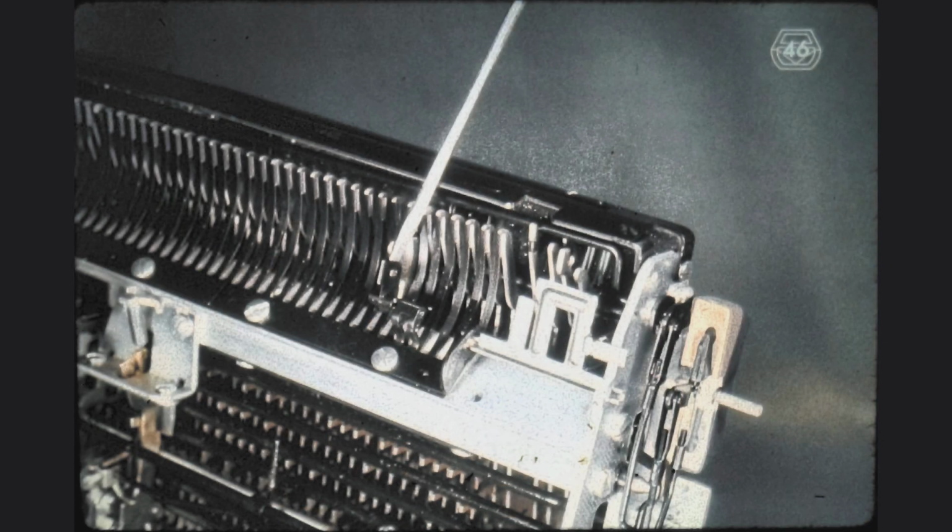To bring about the near vertical movement of the spacebar, it comes equipped with this guide. Remove the spacebar guide clip, as shown here, provided that your machine has the same level of spacebar guide. Do not attempt to remove the guide if the step would require breaking any adjustment. Let us first go to the next view. It should then be possible for you to remove the spacebar without disturbing any adjustment.